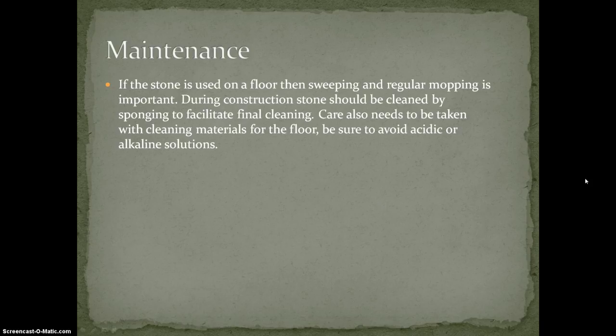Maintenance. Although natural stone will wear better than pretty much any man-made building product, it still requires maintenance and care. If the stone is used on a floor, then sweeping and regular mopping is important. During construction, stone should be cleaned by sponging to facilitate final cleaning. Care also needs to be taken with cleaning materials for the floor. Be sure to avoid acidic or alkaline solutions as they will eat away at the floor.